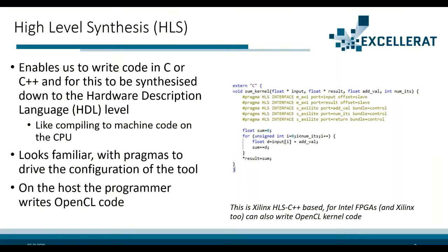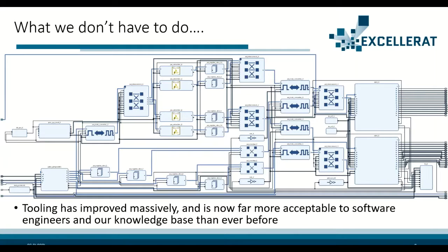If you've at all seen or used FPGAs in the past, you might have seen something really nasty, such as this diagram here. This is called the block design. In the past, what we had to do is manually connect all the different components together: things like the external memory with memory controllers, our own kernels over here, and then connections to the outside world. And again, we don't need to do any of that anymore. The tooling is mature enough so that it will generate all of this for us.